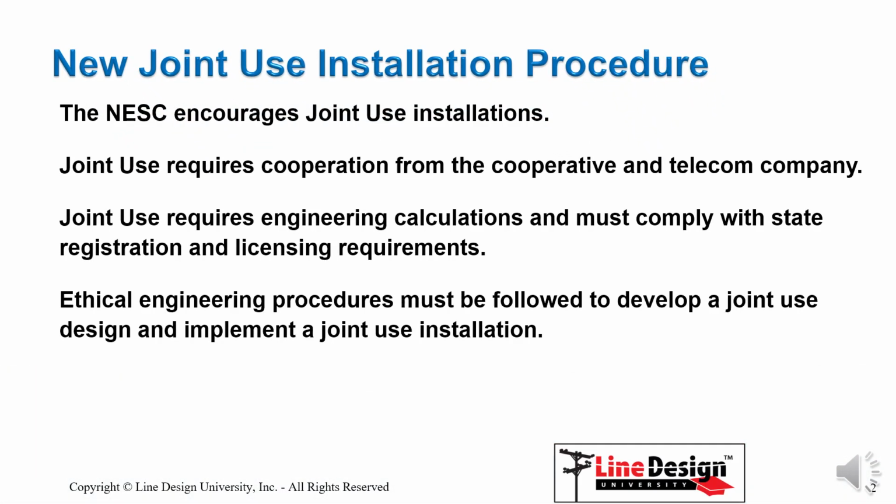The NESC and several regulations encourage joint-use installations, which requires cooperation between the rural electric cooperative and telecom company. Joint-use installations increase the transverse wind load and increase loaded design tensions on the cooperative power poles. Because of this, calculations need to be performed to determine NESC compliance.